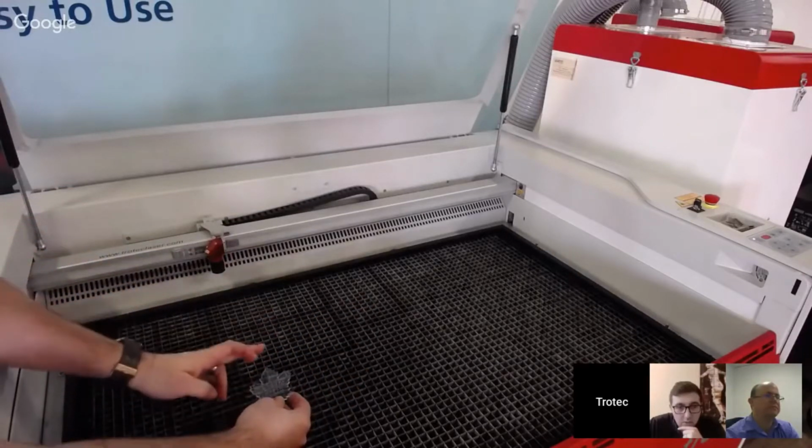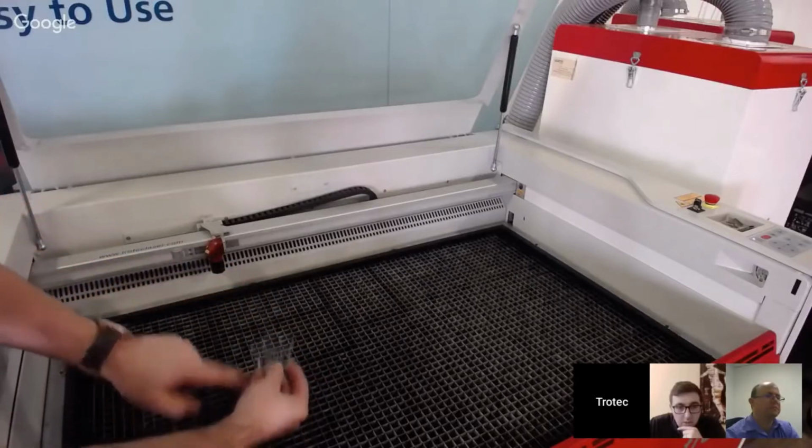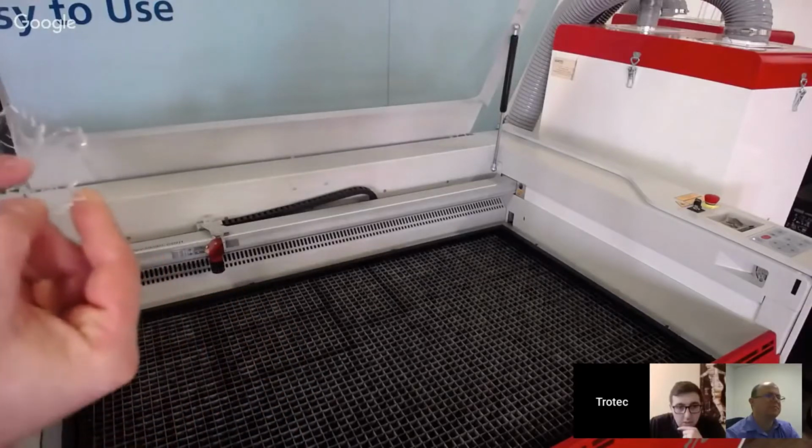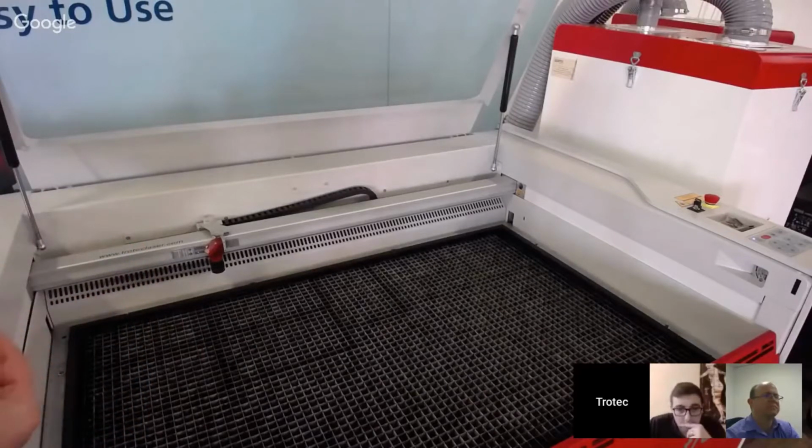If you were to start from the top and that smoke is getting dragged across, those fumes are going to get caught in the actual depth of your engraving, which is why you'll get those sticky residues and discoloring of your engravings.